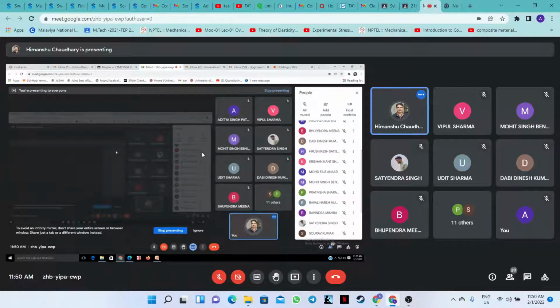For a planar link, suppose a slider crank mechanism with a connecting rod, this is planar motion. Planar motion means no motion in the z direction. Of course, the link is rigid and three-dimensional, but for each point on the connecting rod, variation in the z coordinate is not possible. That's why it is known as a planar link mechanism. How many parameters are required to find the position of the connecting rod?